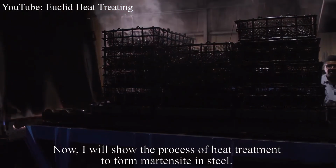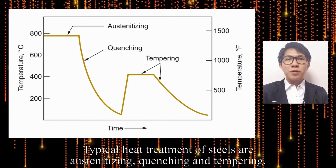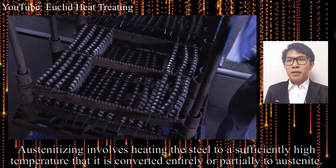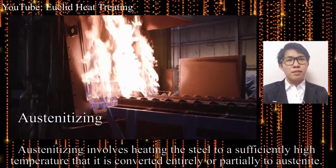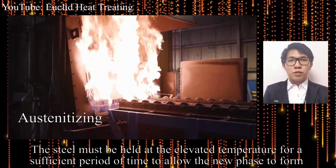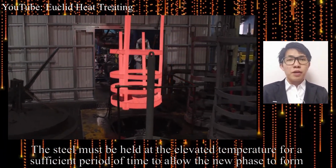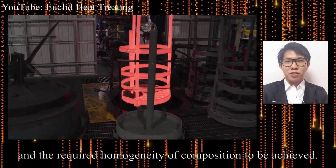Now, I will show the process of heat treatment to form martensite in steel. Typical heat treatment of steel are austenitizing, quenching, and tempering. Austenitizing involves heating the steel to a sufficiently high temperature that it is converted entirely or partially to austenite. The steel must be held at the elevated temperature for a sufficient period of time to allow the new phase to form and the required homogeneity of composition to be achieved.